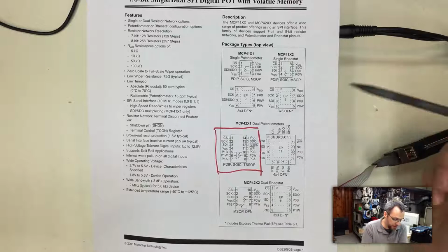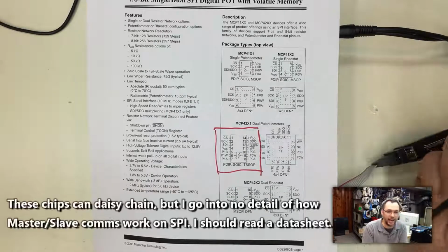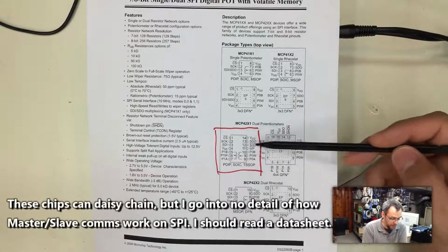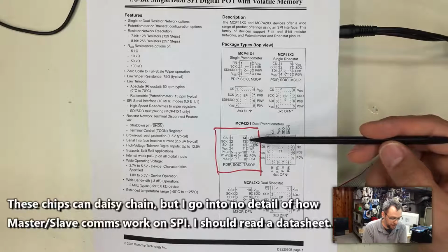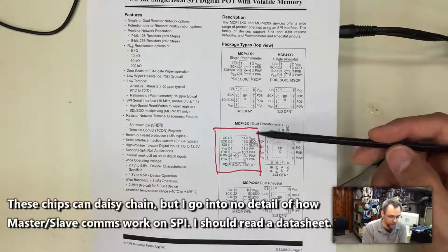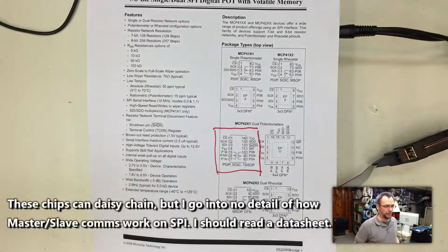There are a lot of other pins here that I'm not using. The SDO, because SPI is designed to connect a whole bunch of devices literally serially, so the SDO, basically when it receives bits on this end, it then clocks them out on the other side. I believe this chip does it 16 clocks later, so that you can daisy chain chips together almost like a shift register, and shift them out of one chip and into another chip if you want.